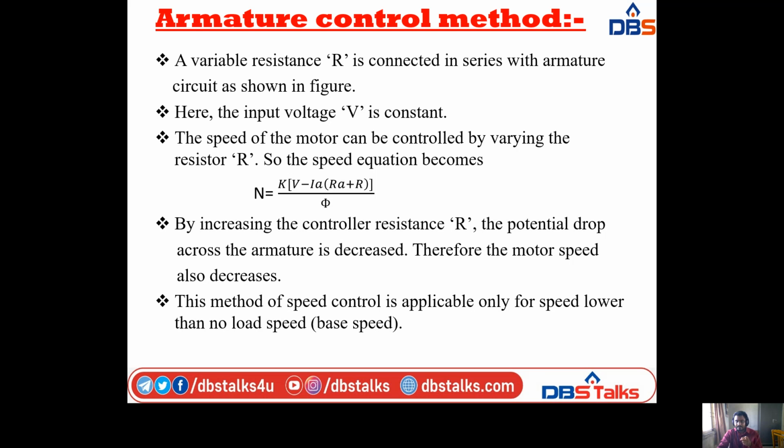Here I am inserting the controller resistance R, so the equation becomes N equal to K into (V minus IaRa minus IaR) by phi.